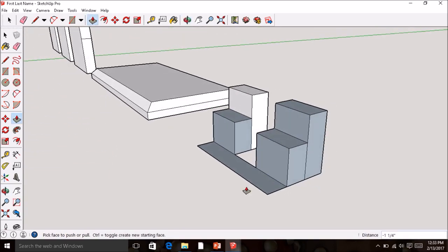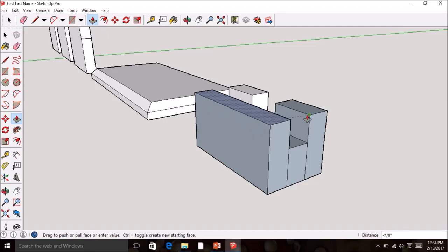Now, we have to move this front piece up, but it's going to tell us we can only move it so far. See how it won't let me go any farther than that first piece? This is what they call an offset limit. It's fine. Go ahead and move it to this first corner. Then grab it again, and it will let you move it to this second corner. So we simply went from down low to this endpoint, clicked it again, moved it up to the upper endpoint.